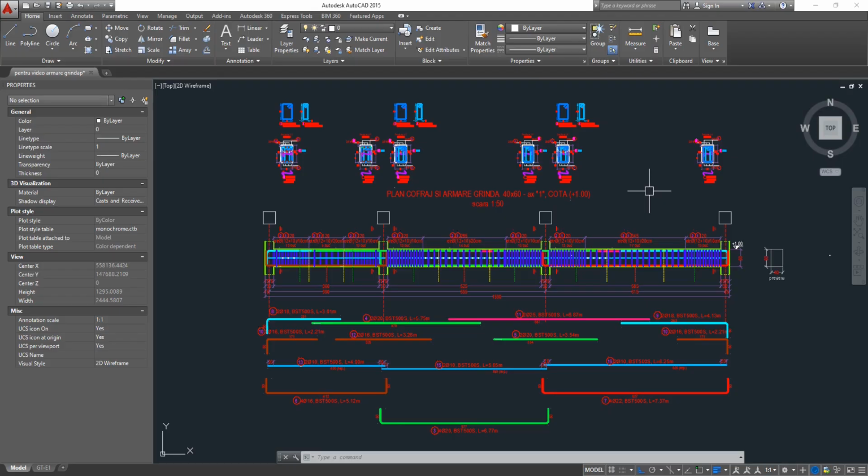You can use it with or without the Lisps, you will see, but better with the Lisp, because the Lisp makes the dynamic blocks work together, transmit data between them, and adjust the dynamic blocks faster and more precisely than you would ever do by hand, which is a huge step in front of the classical AutoCAD, which, I'm saying it again, is just one step ahead of pen and paper. It's just an electronic drawing table.